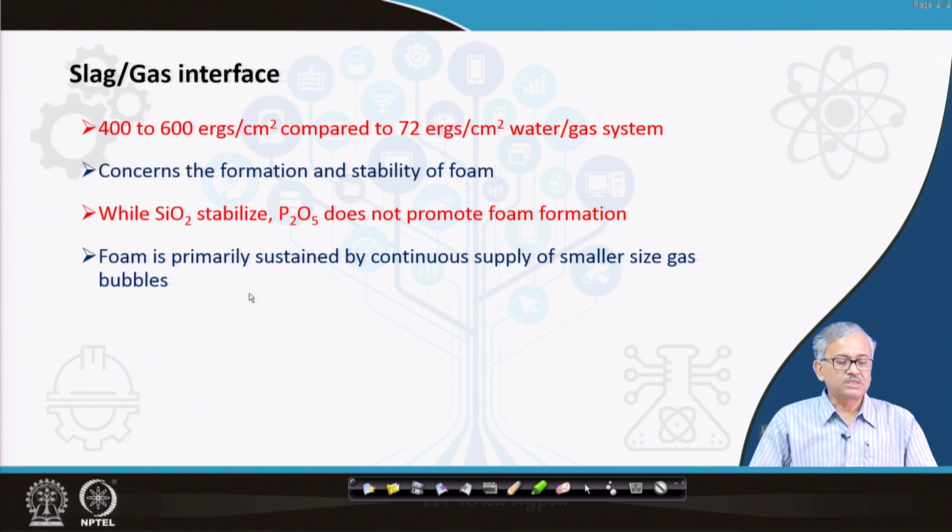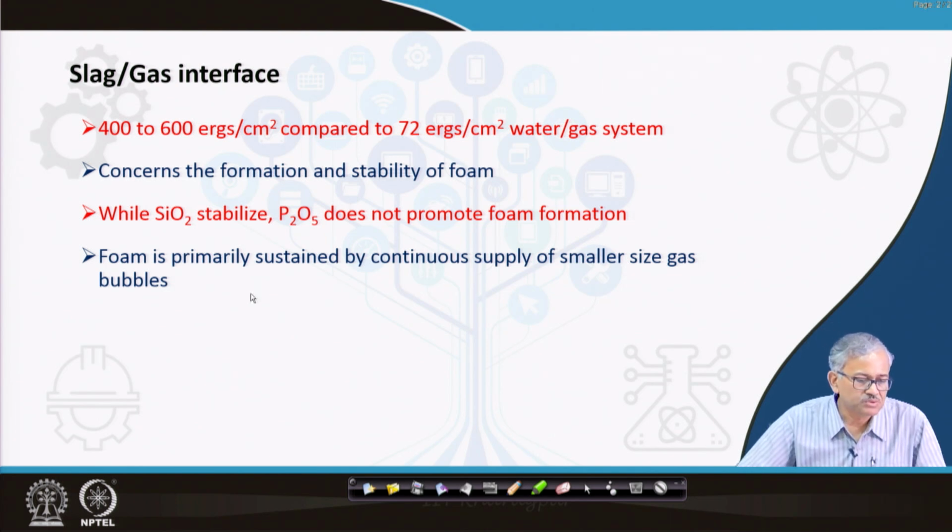So that's why in LD refining you have to continue the decarburization to the end of the refining, because if decarburization stops, that is if you finish your carbon, then no carbon means no CO generation, and the emulsion will collapse. Because whatever you do, surface tension, whatever you decrease and all these things, finally if you want to stabilize the foam, the CO has to be supplied continuously.